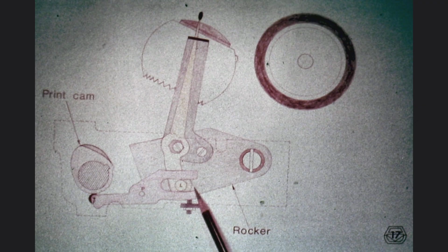However, when the impression control lever is set into position 5, the situation is quite different. The distance of travel for L, the load, is now substantially larger. The stud at the bottom of the impression control lever would then be approximately in the position indicated by the pencil. The travel time for this new condition is still determined by one of the lobes of the print cam, which remains the same.